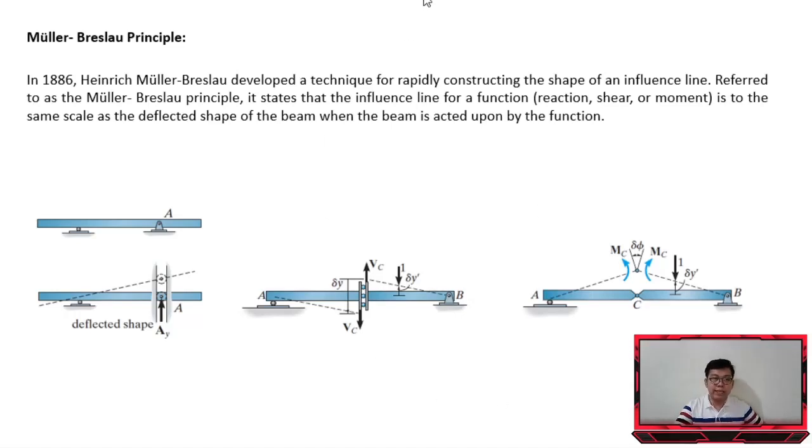In this method, guys, instead of what we did earlier, notice that we took the ordinates and then drew the diagram. We got the ordinates, be it using the tabulated method or the equation. Ordinates, then diagram. Now, in this method, the nice thing is the diagram comes first and the ordinates later, which is much easier. Once you already have the diagram, solving for the ordinates is easy.